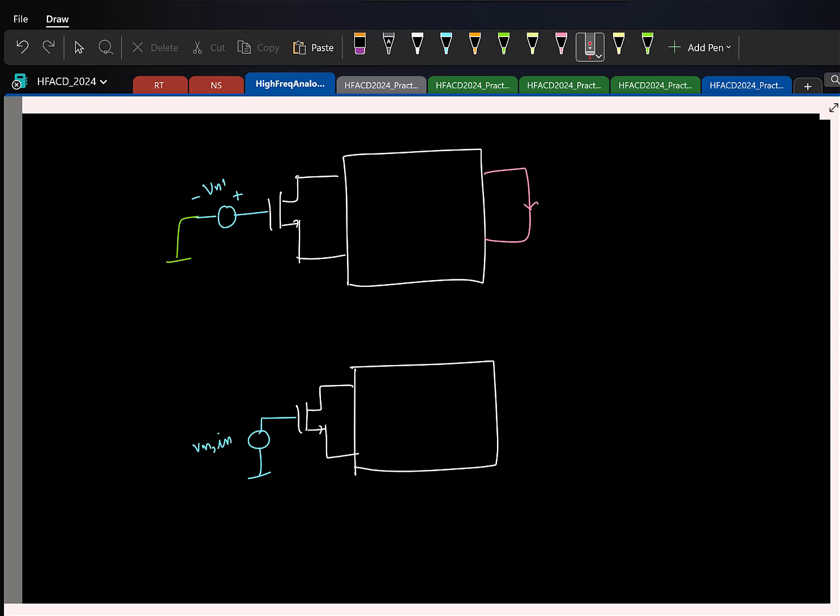That should also make sense because you are going to apply the actual input signal here. So the input is basically getting added to this noise. So that is basically your input referred noise. Is that okay? So for all our op amps, the input referred noise will have contributions from all transistors. But for the input differential pair, the contribution to the input referred noise voltage is basically the corresponding noise voltage for the transistor. So that's one straightforward result.